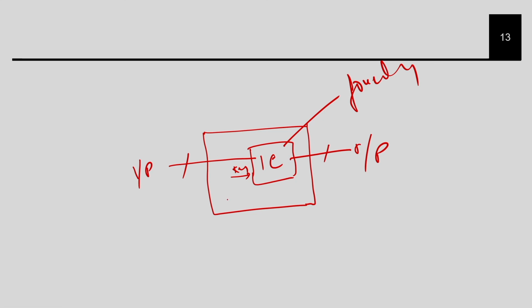Once I get the IC from the foundry after fabrication, I will create my system like this. I will put in a tamper-proof memory, where I am going to store the key. Then I package it like this, and this is the system that I give to my customer. So once you buy it from me, the key is already embedded in your system and it is tamper proof, so you cannot go in and check the correct value of the key. If you buy it from me, the circuit will work, because I have already embedded my key into the actual circuit that I am selling to you.